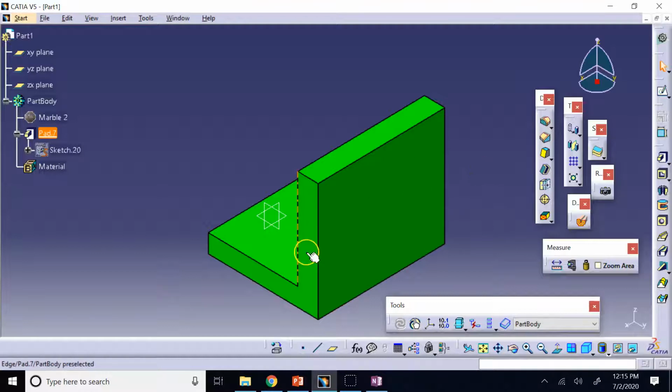Now, of course, we can rotate the object too. I'll show you later here that you have the rotate feature. We can rotate it, but then you have to rotate everything else. So I recommend you go with changing the sketch plane if you catch it early on.